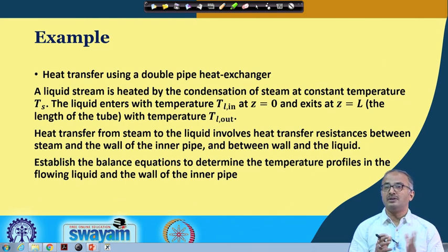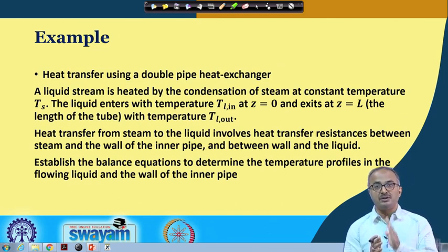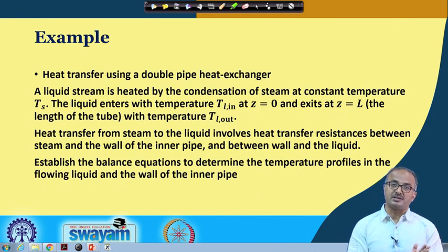Generally you know, whenever the heat is being transferred from a given fluid, the fluid is supposed to get cooled down. But when we are talking of a saturated vapor, then you see that if the saturated vapor is being condensed and it is going to a saturated liquid state, then during this process what we find is that the temperature would remain constant if the vapor is of a pure component.